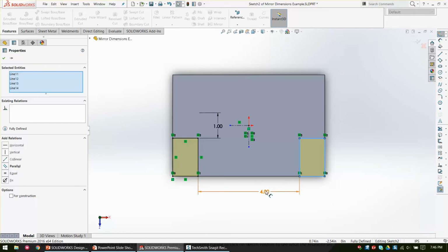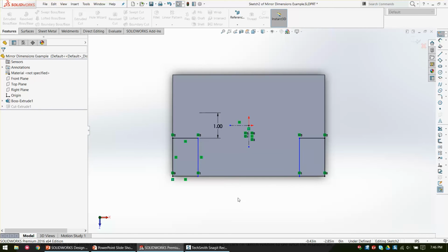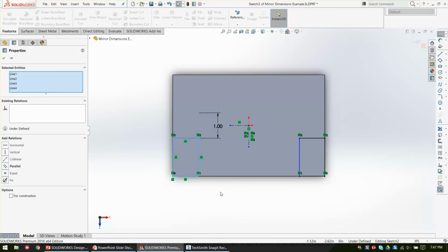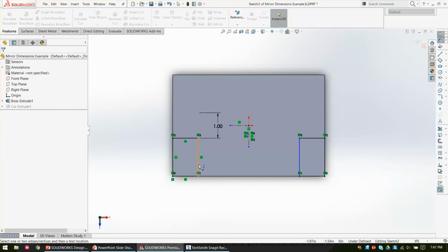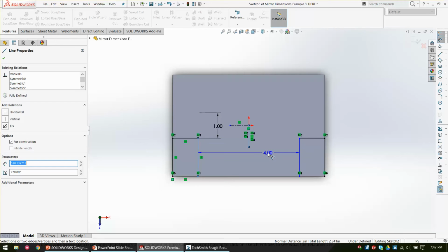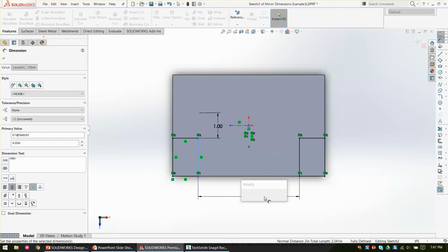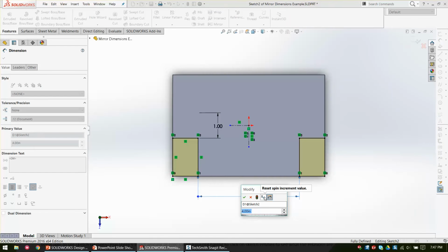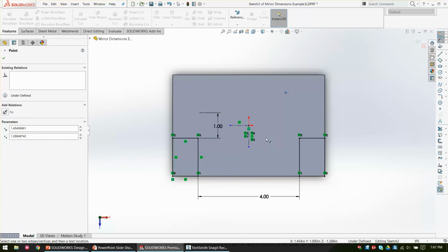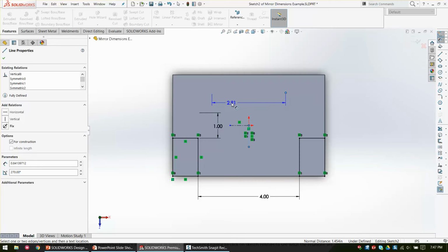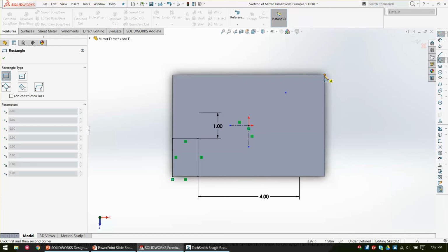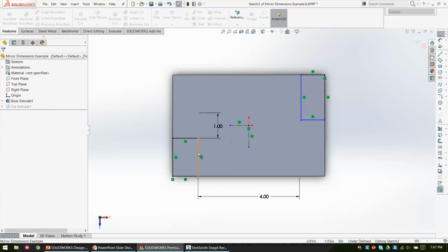So what we ideally want to do is we always want to model our sketches on one side in total isolation. And I can do that by clicking the center line and moving the sketch to the other side, and it'll give me a double dimension. This is often used in like radiuses or revolves for your diameter versus your radius, but it works in every feature. Doesn't have to be just revolves. Anytime you pick any object and then pick a center line, it'll double your dimension based on what side of that center line you put your cursor. So I think the reason why I originally had this rectangle up here was so that I could show that.